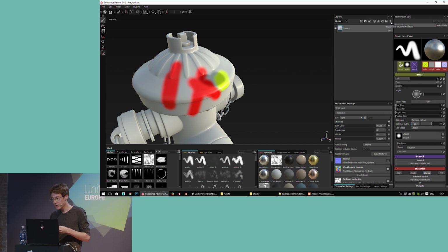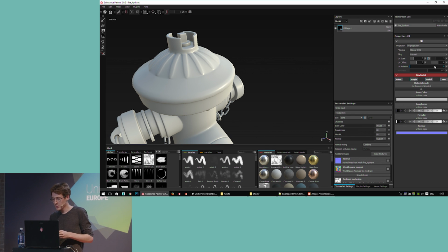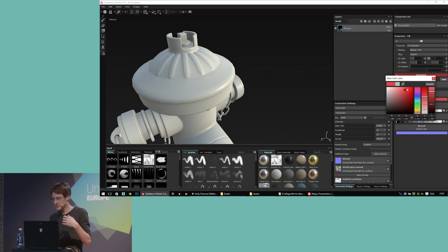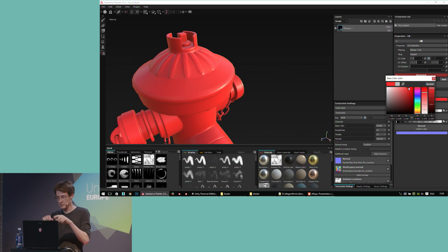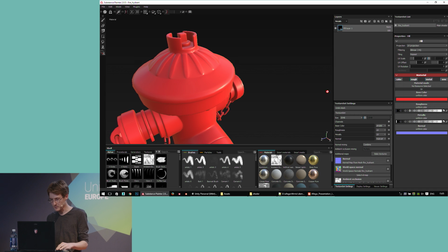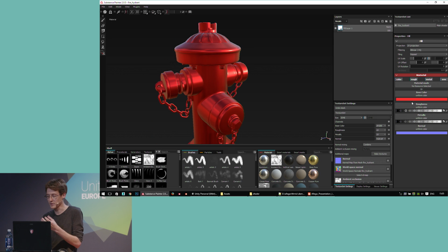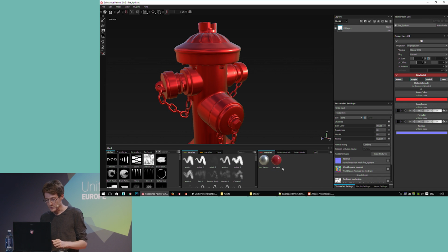But nowadays, we mostly rely on what we call fill layers. It's this button here. It will simply fill the entire UV space with a content. By default, the content is uniform colors, like in this case, uniform color for base color, roughness, and metallic. This way, you can very quickly define a very simple material. But you can also use substances.